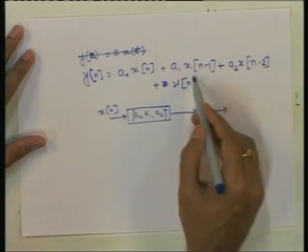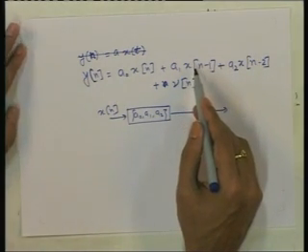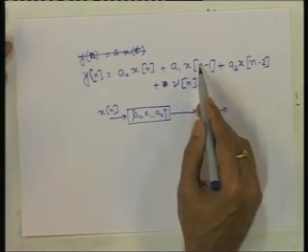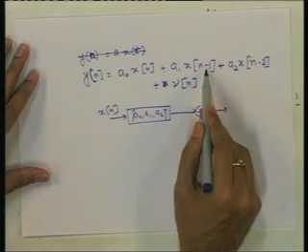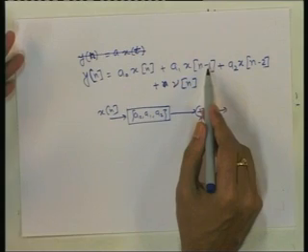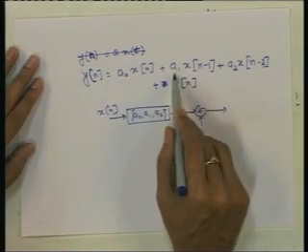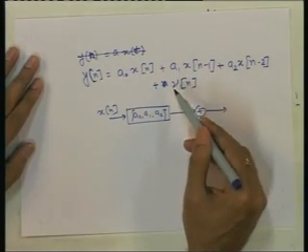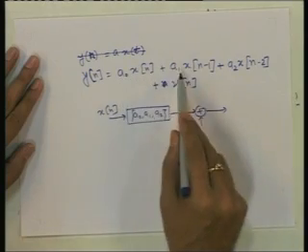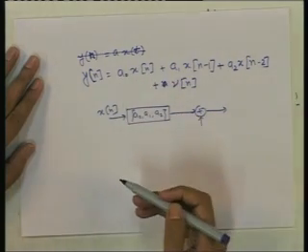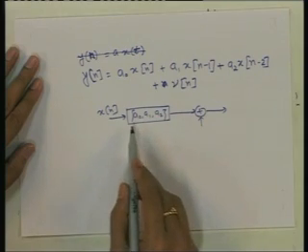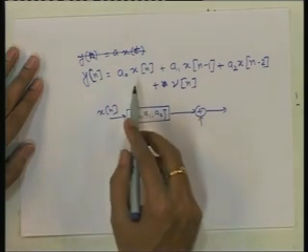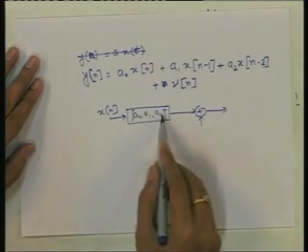This path may be there at some point of time, there may not be this path at some other point of time, because some reflector might have been there before and it may not be there now. So, a1 may be 0 at some point of time. So in general, all the channel coefficients are changing with time. So, there is a multipath channel, and the filter itself is changing with time.